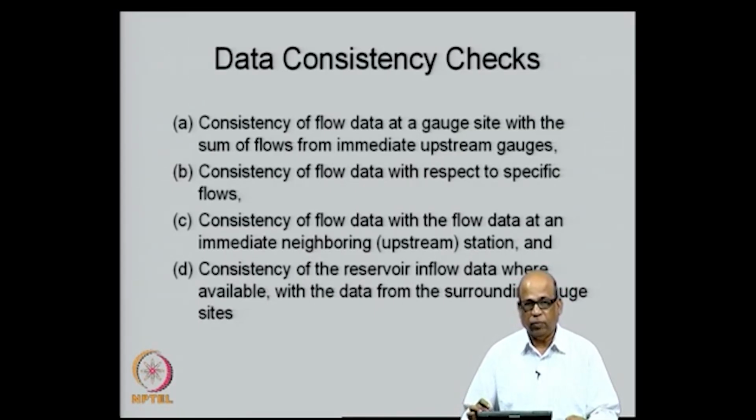So, the first step that we do in any hydrologic analysis is to look at the time series of the observed data and look at the breaks that have happened in the time series for several reasons. One is the data itself may not be recorded, or the data may be wrongly recorded and therefore, it has been taken out of the record, or there may be some gaps or breaks that cannot be explained in the time series, and therefore, the breaks have happened. So, the time series of data has breaks in between.